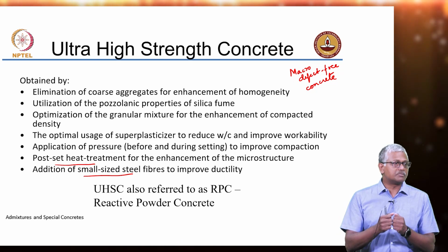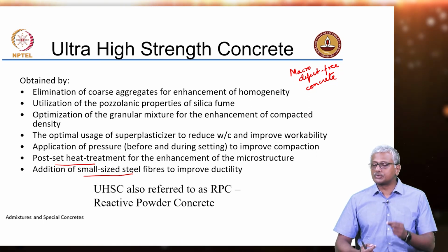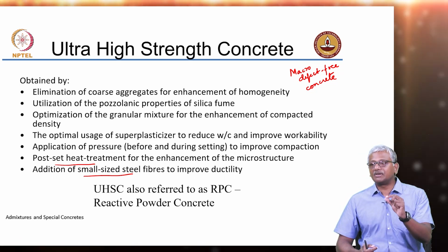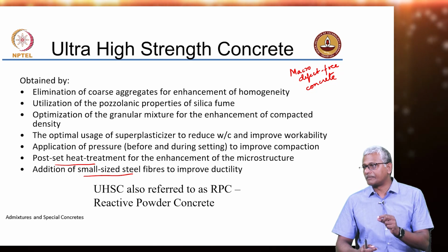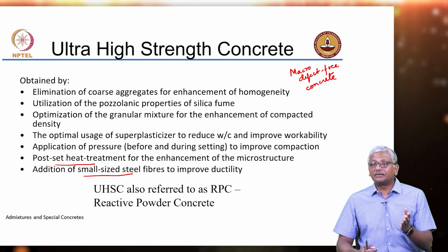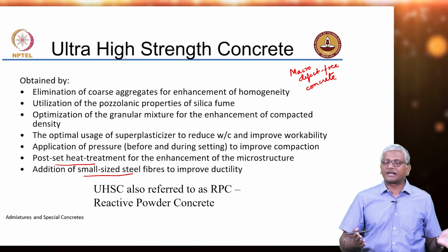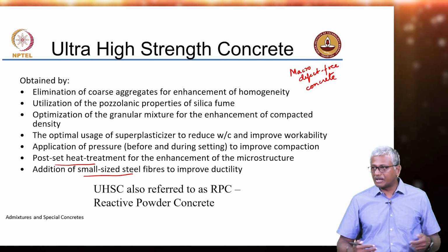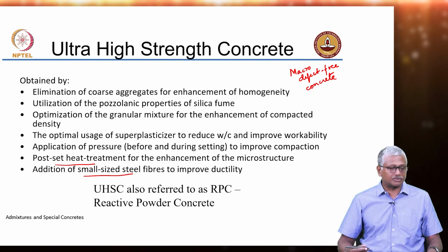They bridge the cracks and prevent the cracks from opening up. Right. So when the fibers used are extremely small sized, they will also be very effective in bridging cracks that are extremely small, right? And you know that cracking initiates in concrete with the micro cracks that are generated first, and if you have fibers to bridge the micro cracks, you will further enhance the strength of the concrete.